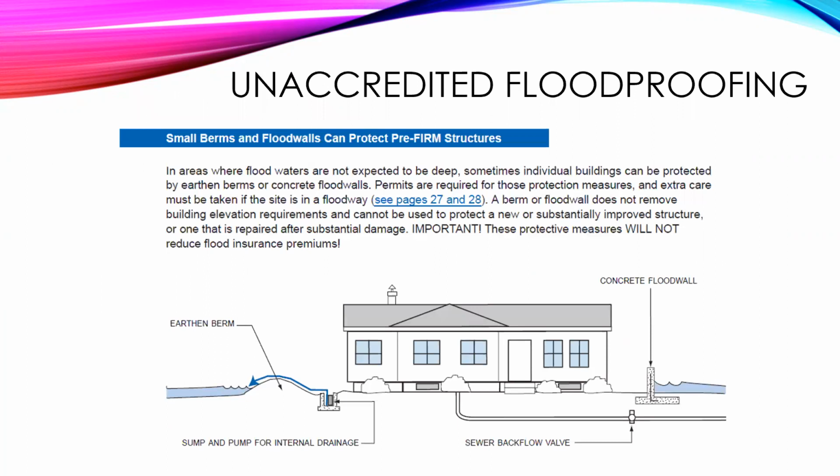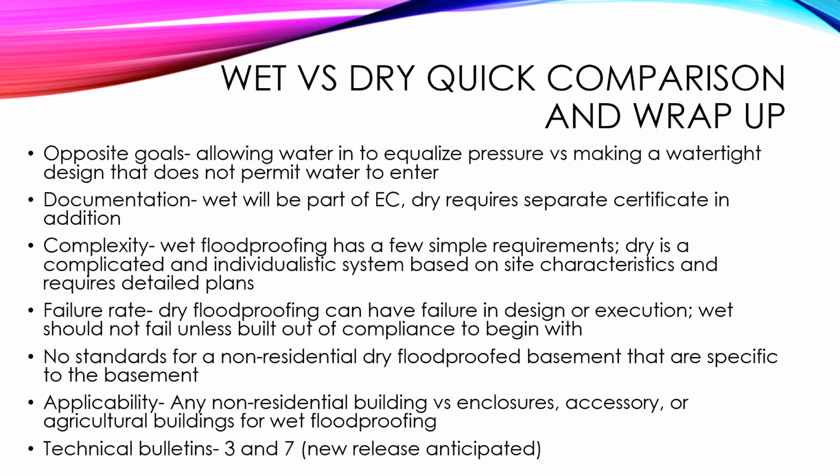But other than that, we are always encouraging people to use other floodproofing measures. It doesn't help with the insurance premium, but if you can, putting in berms, using the backflow valves, having flood walls, whatever you can do to divert water away from a structure is still valuable as far as not getting water in your house or the business or whatever the case. Those types of measures are still useful.